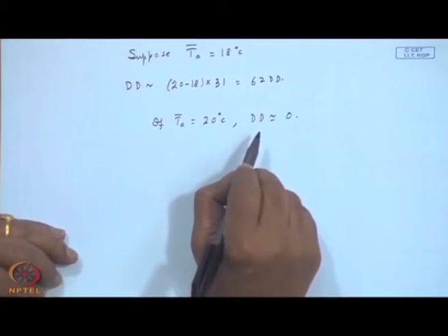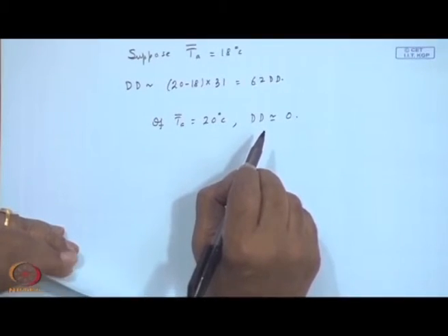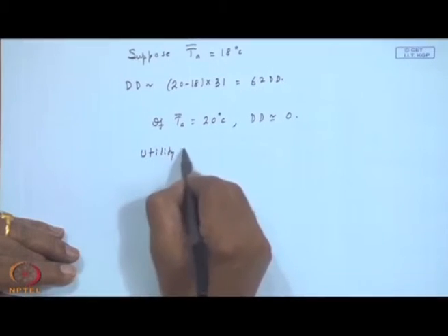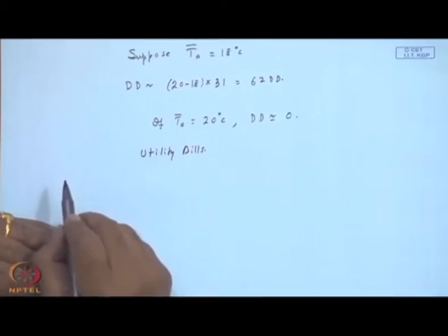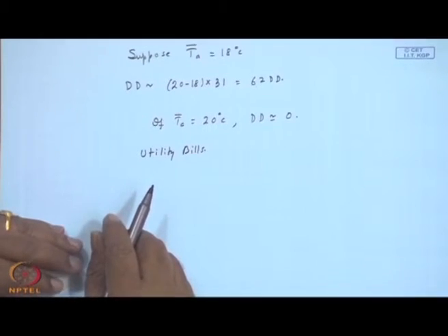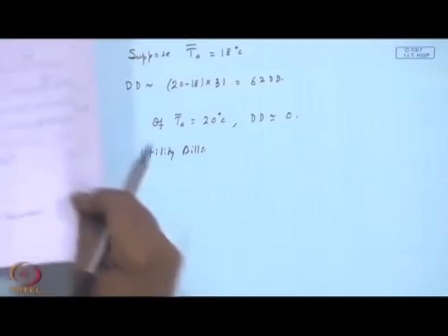So, for degree days calculation, the best thing is if you have the hourly data file, one can compile it or depend upon the utility bills. So, if heating required so many kilowatt hours of energy and you paid so much, that much is the space heating load. So, what I wanted to demonstrate was basically you can calculate with the monthly average hourly data available reasonably well, and it works if the ambient temperature, even the daily average, is less than 15 to 12 degrees.